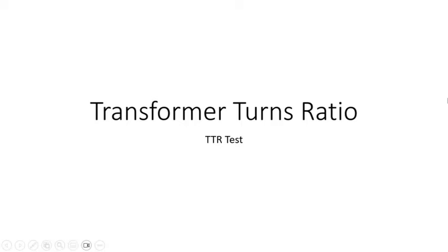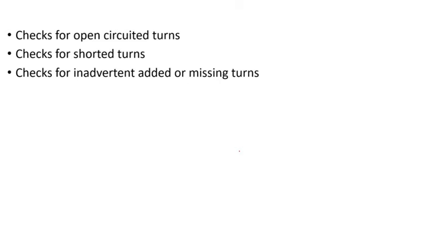In this video, I'll talk about transformer turns ratio. Some people in industry will refer to it as TTR test. This is an important test, because the way transformers work is induction, electromagnetics basically, and you have turns on the high side, turns on the low side, and that's how you transfer from one voltage to another.